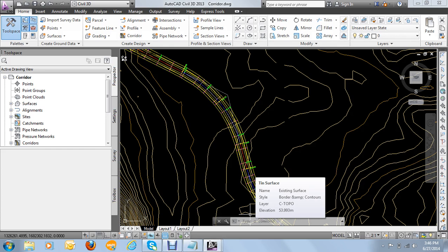Yeah, of course, when you are creating a corridor, first of all the surface should be known. It means you use certain data. Maybe you imported the data, or you created a surface from a point file. Then you created an alignment. Before you create a profile, you cannot create a profile without having a surface and an alignment. So those should come first. And when you create an assembly, it does not depend on anything.